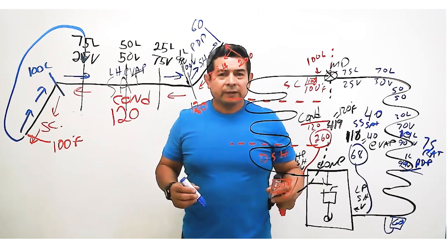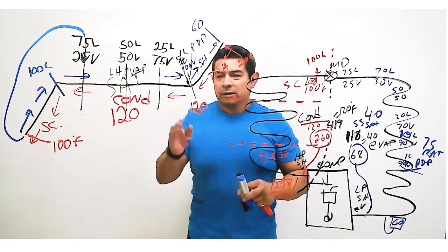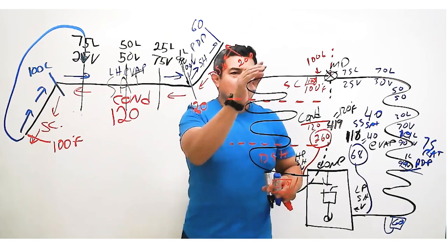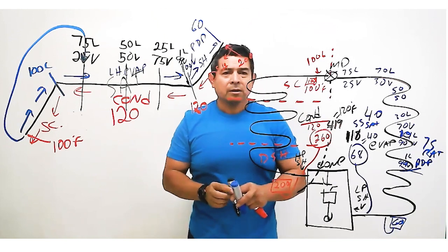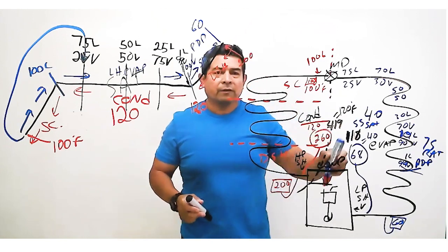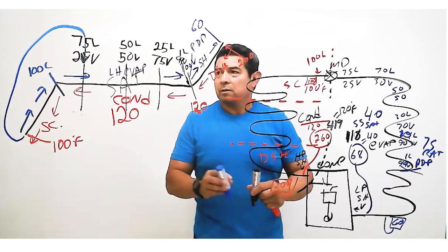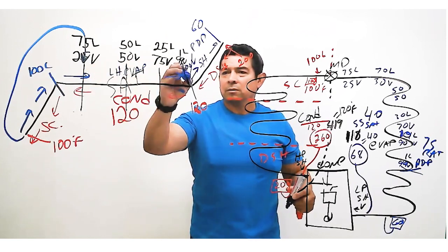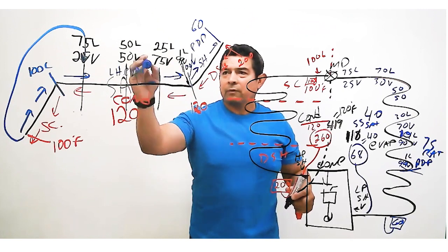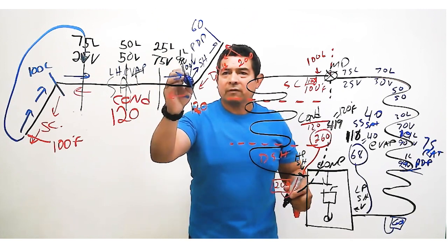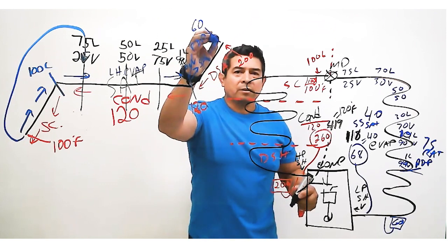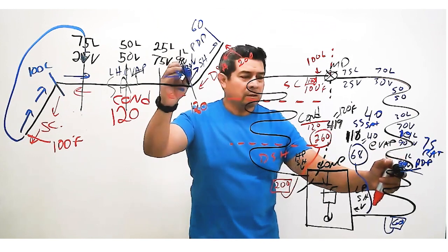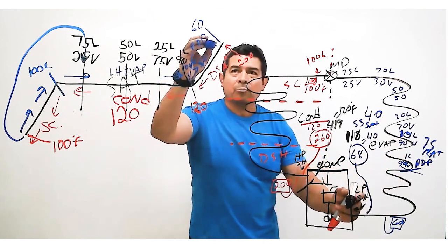Looking at a metering device, it's coming in at 100 degrees, and then in a space about an inch or two, it's going to go from 100 down to 40 degrees because of the flash gas. We go into the evaporator and evaporate it, so we're adding latent heat of vaporization. After all of that refrigerant has boiled off and we're at 100% vapor, we start to superheat it from the predetermined point, which is right here, all the way up to the compressor.